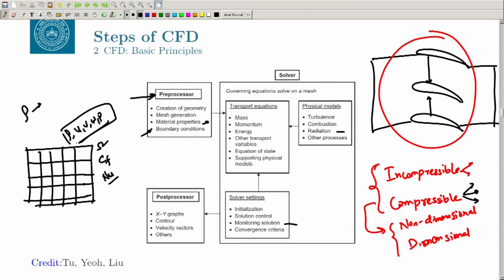You have the grid and you have these variables, so you can calculate those gradients and plot them and see how it looks. You can have line plots, let us say across the center line. If you want to see the 2-dimensional thing, you can make a contour. If you want the 3-dimensional thing, you can make an isosurface. You can have velocity vectors, how the velocity is changing, and streamlines. You can plot all these different kinds of things for understanding the results of your simulation.